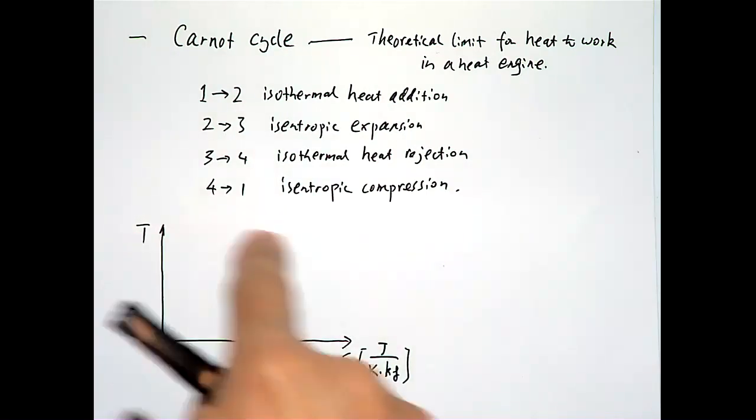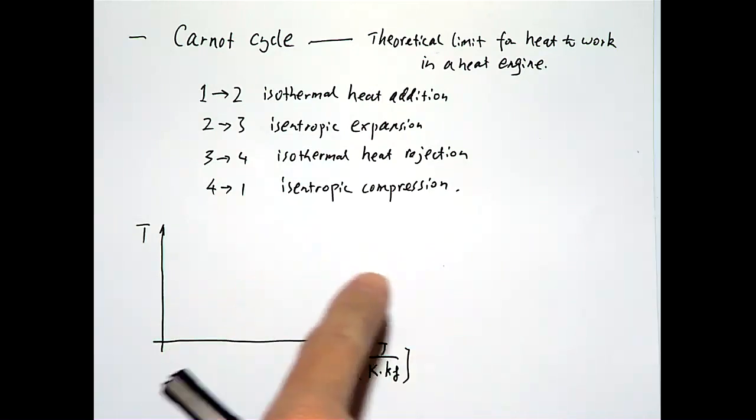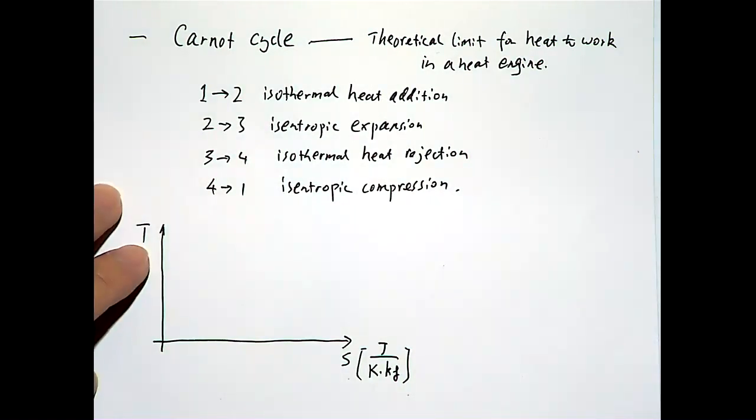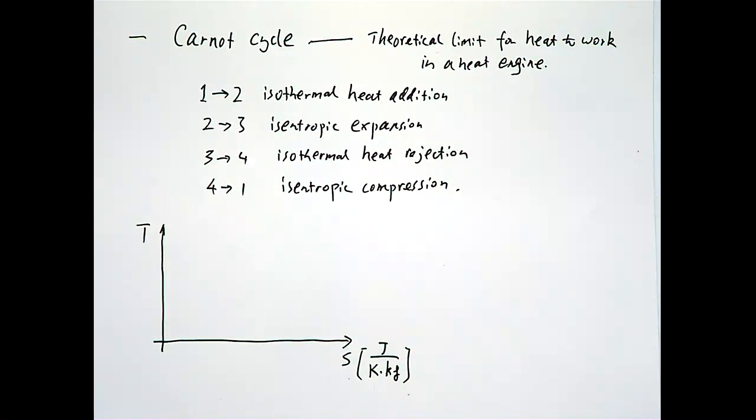We consider temperature and entropy certainly independent, and temperature is intensive, and if you normalize by mass, the entropy is also an intensive property. So two independent intensive properties can describe the whole process. So that's the starting point here. So we choose the TS diagram. It can be drawn by different combinations of parameters, but we use TS here.